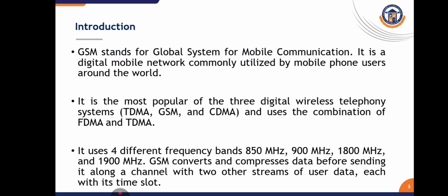So, introduction. GSM stands for Global System for Mobile Communication. It's a digital mobile network commonly used by mobile phone users around the world. It is one of three popular digital wireless technology systems: TDMA, that is Time Division Multiple Access, Global System for Mobile, and Code Division Multiple Access. It uses a combination of Frequency Division Multiple Access and Time Division Multiple Access, and it uses four different frequency bands: 850 megahertz, 900 megahertz, 1800 megahertz, and 1900 megahertz.